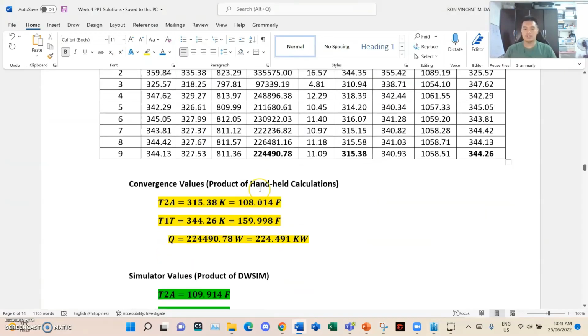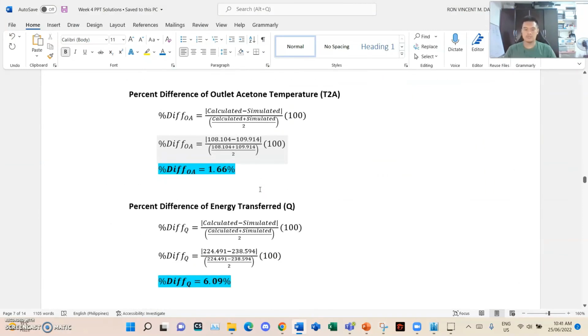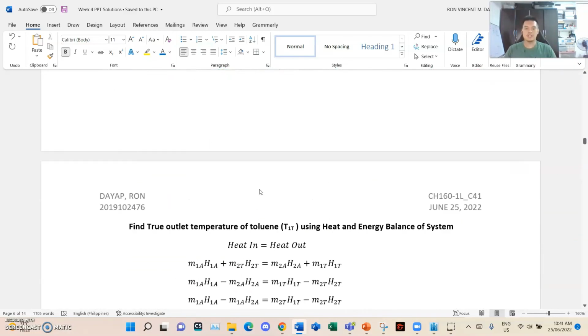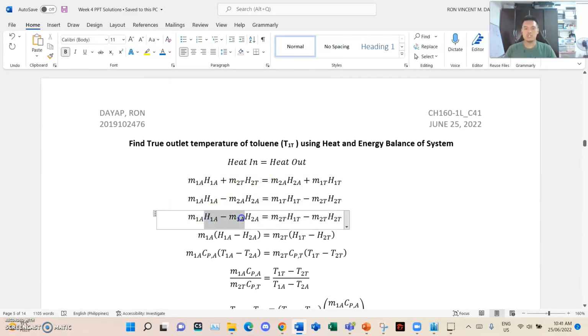Another reason for the slight variation might be the rigorousness of the calculations, because remember that I assumed for the heat balance, which normally is truly enthalpy, to be Cp delta T, meaning that heat capacity is simplified.